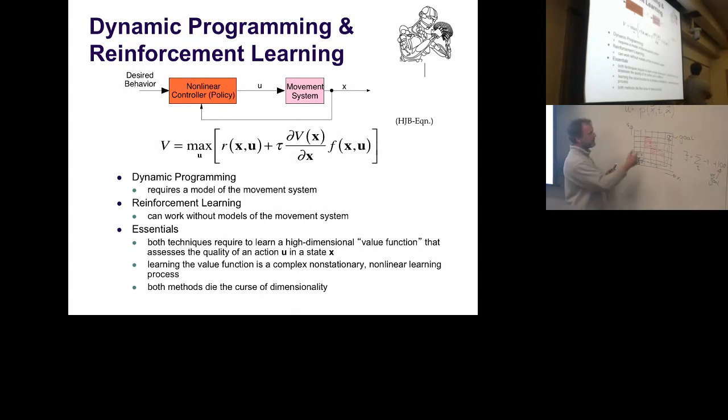In reality, what people do is they compute this backwards. So you start at the goal, basically, from here to get to the goal, from here to get to the goal, from here to get to the goal. After I'm done with this, I do all those states, and I sweep backwards, and this way I can compute what's optimal. So people have seen this most likely as Dijkstra's algorithm to some extent before. It's a part of dynamic programming. There's generalized versions to that. The world of dynamic programming, reinforcement learning, has its own versions of doing that. But that's the idea. You basically try to chain backward what is optimal and compute what is optimal. It's much, much harder to do this, unfortunately, in continuous systems.